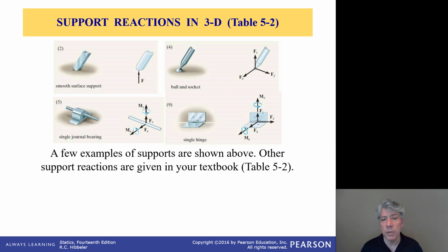Obviously, things would be a bit different if it's a bearing that is designed to accept thrust loads. Some are. Most of the time, they're not. So you have to know a little bit about the bearing or just make some assumptions. The safest assumption, the best practice, is to assume that you're only going to have forces Fz and Fx.